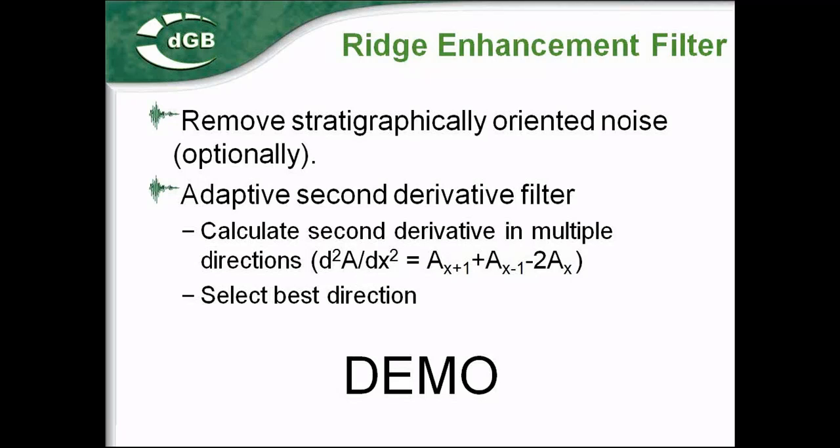The equation for that, I do want to mention that, is the second order derivative is numerically expressed as shifting one sample up or in front, shifting one sample back or downward, depending on what you're doing, adding those 2 shifted samples up, and then subtracting them twice by the middle sample.